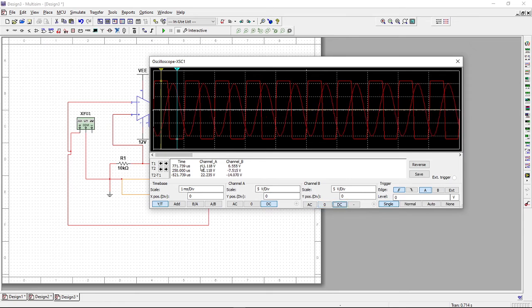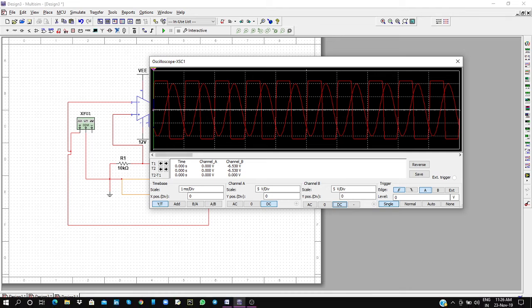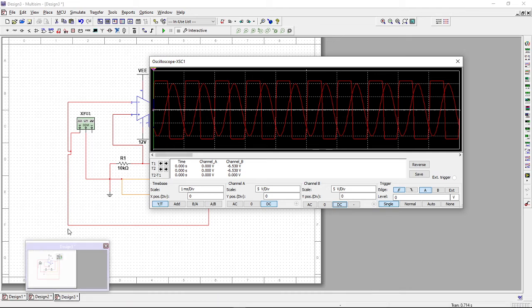Both the waveforms are observed at a time. Here, UTP is measured as the intersection point above the reference, that means the intersection point of both square waveform and sine waveform, which gives the UTP, that means upper threshold point. Again, I will say one sentence: above the reference line, the intersection between both the square waveform and the sine waveform gives the upper threshold point.